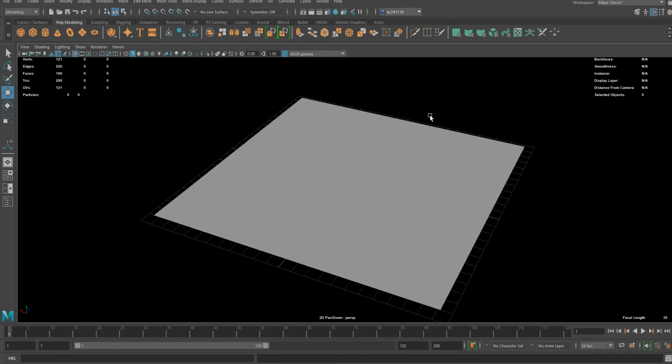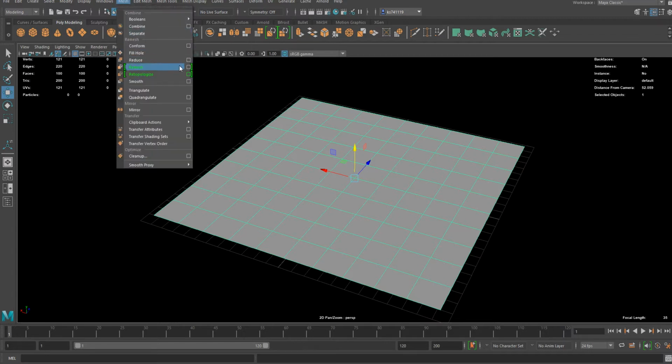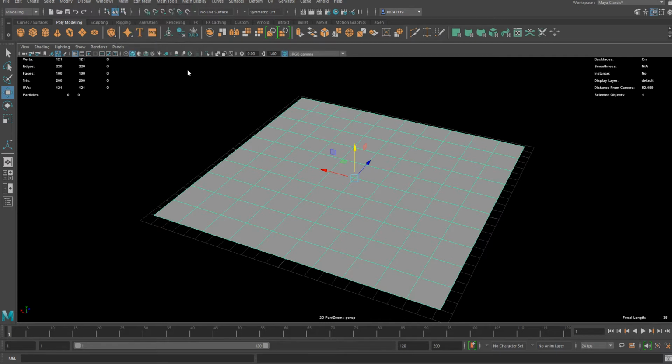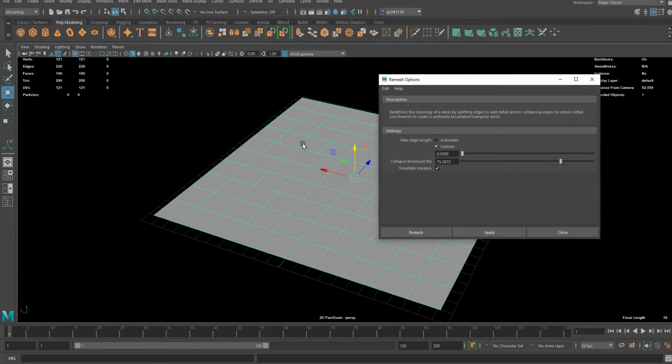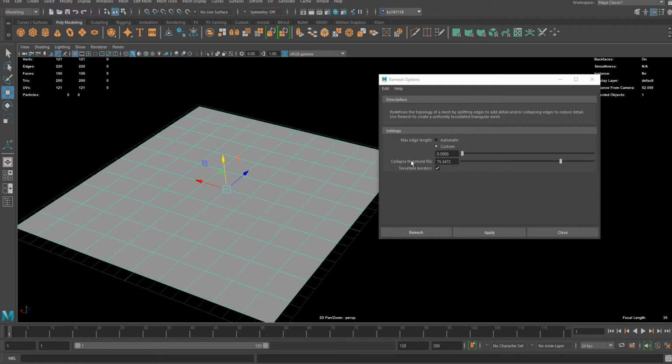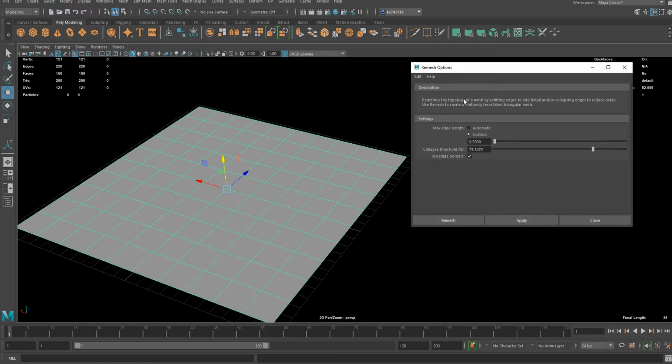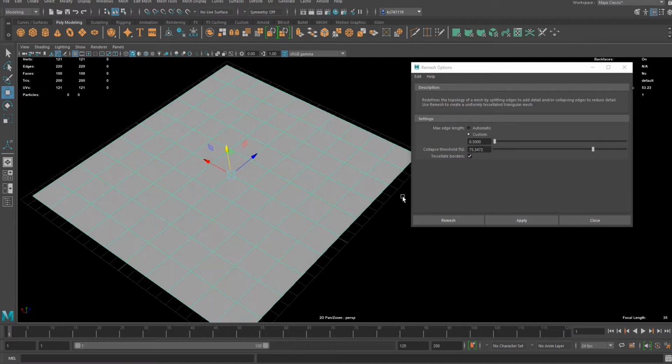In this video, I'm going to show you how you can tear objects using nCloth simulation. For this tutorial, I'm going to use this simple plain object, but you can use whatever object you want to apply the simulation to. So the first step is remeshing this object, because it has two straight edges, which will look too artificial when we tear it. So we're going to use the remesh tool to randomize this topology.